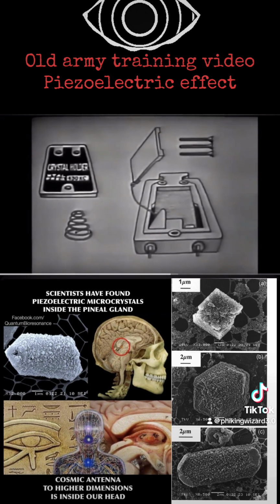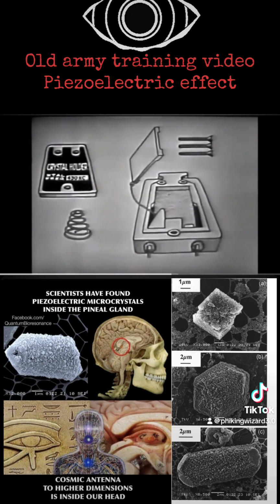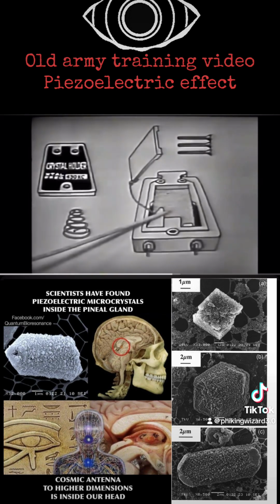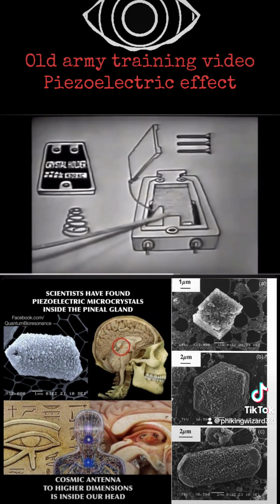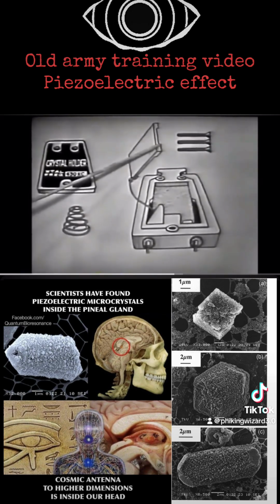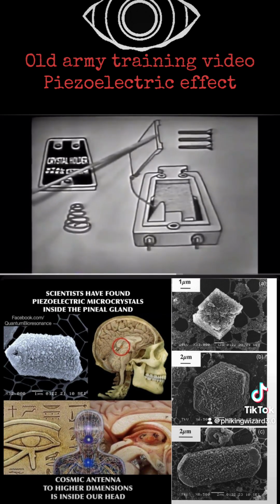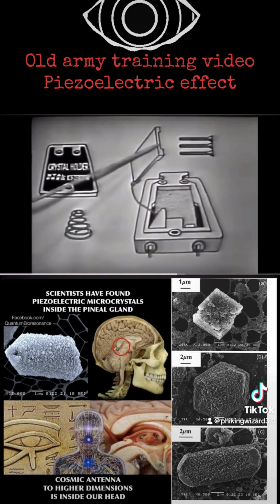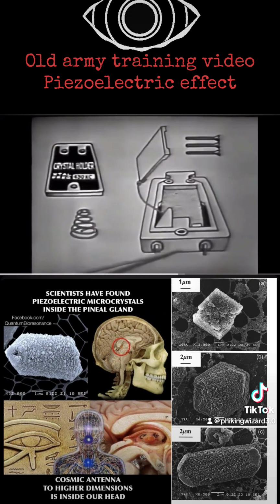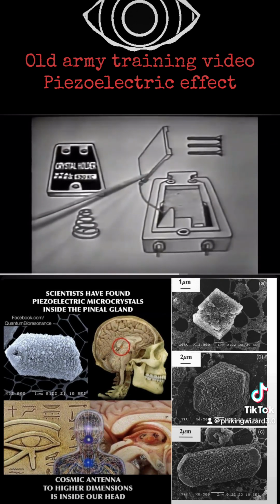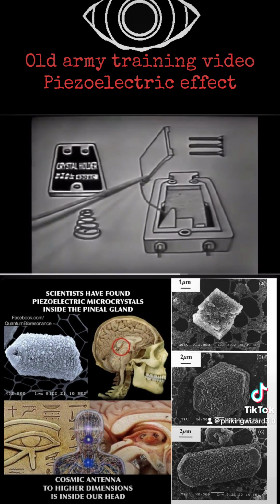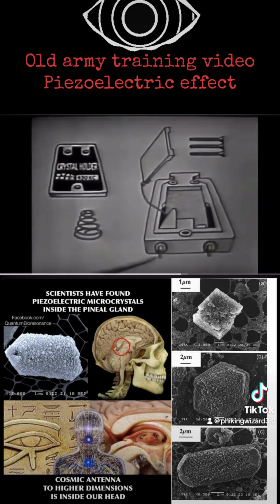The crystal will be placed in the holder between two parallel plates. The plates have an air gap between them, which allows room for the crystal to vibrate. Now these are the pins that will allow the voltage to be applied to the plate. And also the pins will allow the crystal to be connected into a circuit.